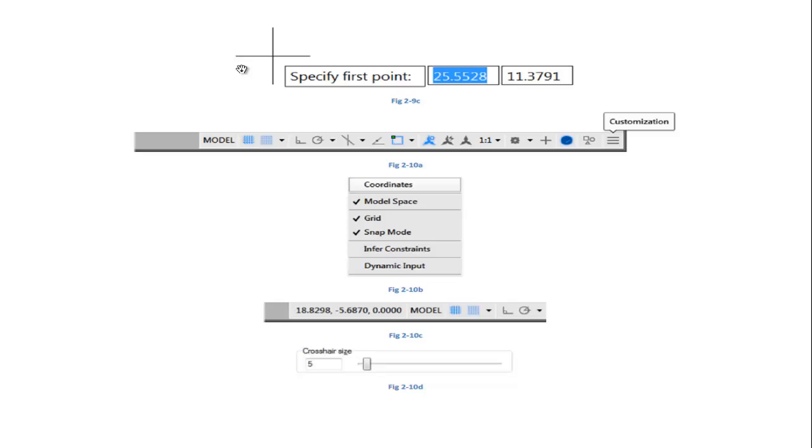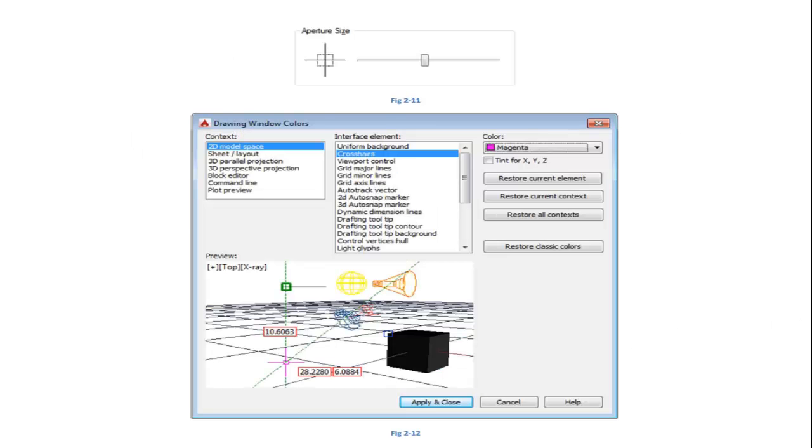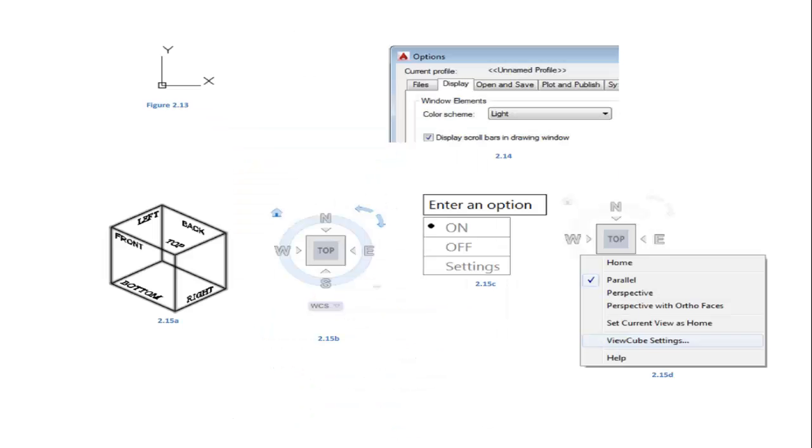If I set a point on the drawing, it's going to go to a user coordinate system, a UCS, and start at 0, 0. So from that point, it's going out a distance, X and Y, or a polar distance, which would be distance and angle. So we can set that up any way we want. Within the model space, we also see the XY coordinates showing up down on the bottom of the screen. And again, we can change the size of the crosshair to whatever you like to use. And we'll push through that. Again, this is going through changing the aperture size and the crosshair size.